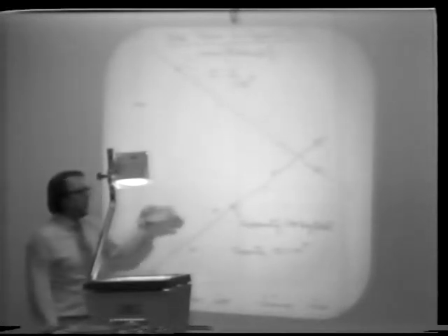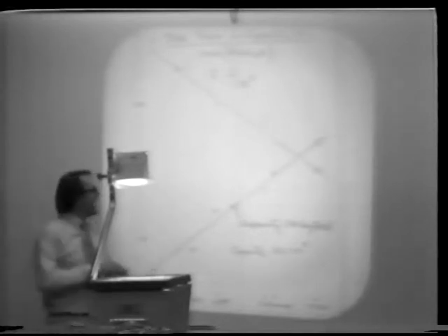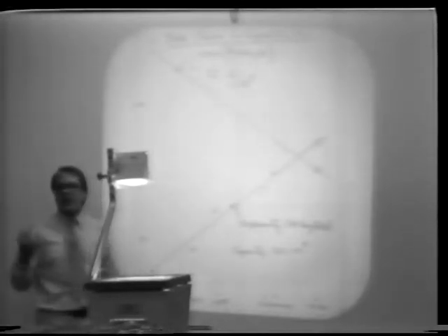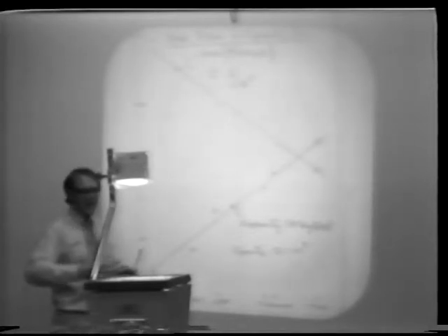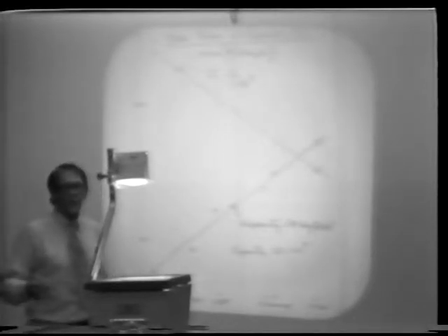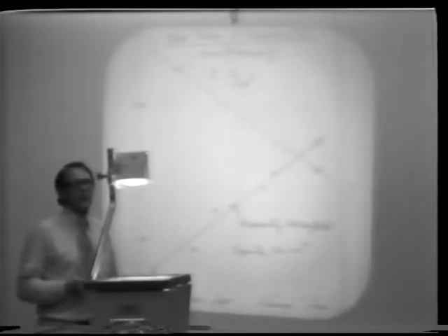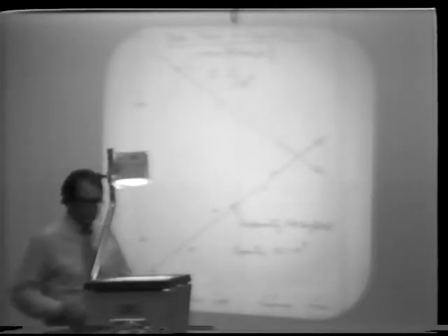So you're sitting there with an established technology, established motor technology, and you aren't able to do very much with the price. Where this has all come about is in magnetic recording density, so that the cost has remained constant, and you've gotten performance out of just packing more on tracks, making better track servos and higher densities in the recording. So they've changed too, but not as rapidly as the semiconductor industry.